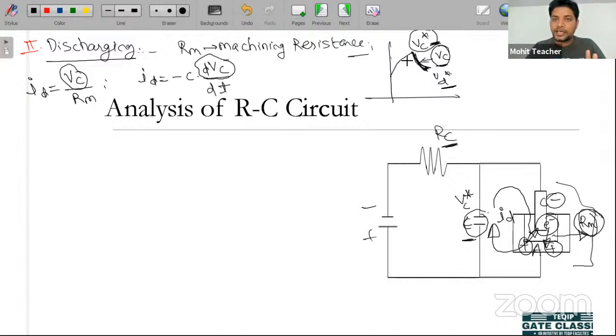Now this change in voltage again, because this discharging is occurring from this point to this point, so this is a change in voltage is nothing but this one only, okay, from VC star to VD star, and minus C, well, C is the capacitance, and we are using this negative sign because you are discharging this one, so the capacitor value becomes negative, okay, मतलब डिक्रीज होती जा रही है, जो कैपेसिटर आपका चार्ज है वो डिस्चार्ज होता जा रहा है, तो that's why we are using this negative value, okay. Fine. So now both the equations represent the value of ID, that is discharging current.